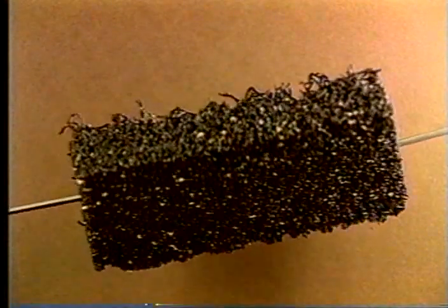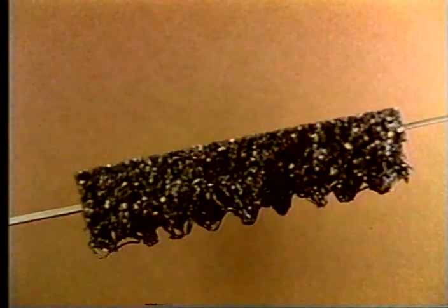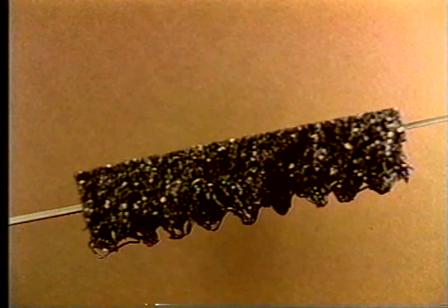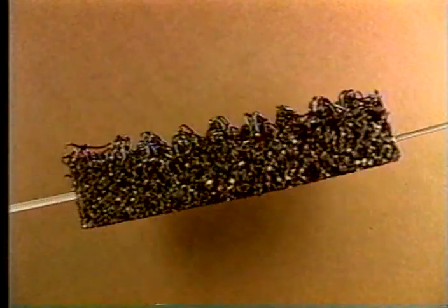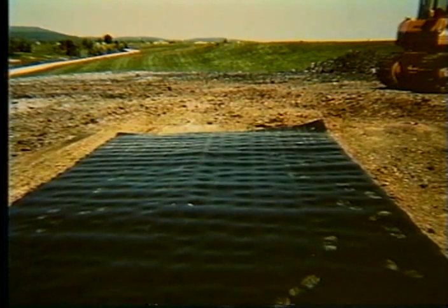This geocomposite is specifically designed to cushion liners. It's made of recycled tire crumb and polyurethane binder in a matrix of fused nylon filaments. Placed below the liner, the smooth side protects it from abrasion while the matrix provides for drainage. Placed on top of the liner with rough side up, the geocomposite cushions the geomembrane against sharp edges in the waste fill.